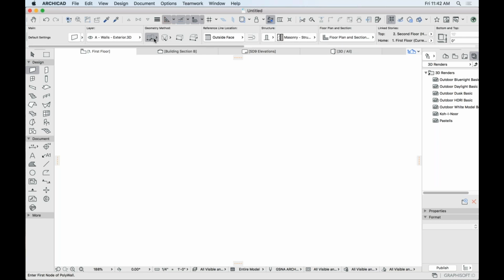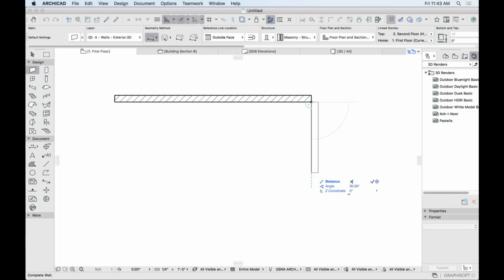If you click and hold your mouse on this geometry method, it gives you even more options. So let's start with the straight wall. We have these 4 items showing up below if I hold my mouse. If I let go on this first one, when I click 2 points or just type in 12, enter, then it's done, right? And now I have to basically click again to start the command again. So then I can click on this corner of the wall and type downward and just type in 4. And you can see the walls clean up where they were touching, but it finishes the command.